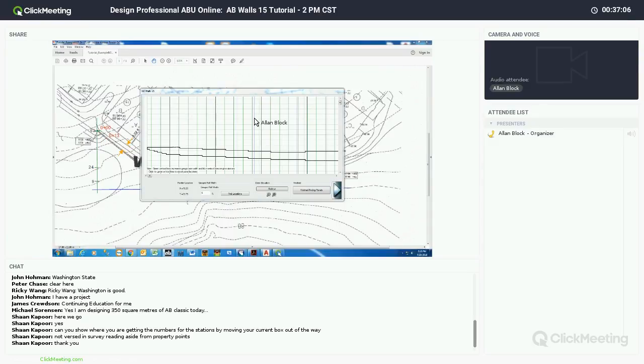What I'm going to show you is how I would cut it based off of elevation of the wall. So in our office, we like to stay around 3 elevation changes, and that's so if you cut and design your wall, you're not going overly conservative.